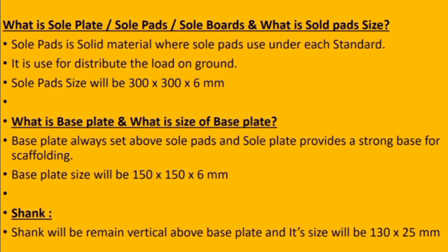What is sole plate or sole pads? Sole pads is a solid material, and sole pads are used under each standard. It is used to distribute the load on the ground. The actual size of sole pads is 300 by 300 by 6 mm.